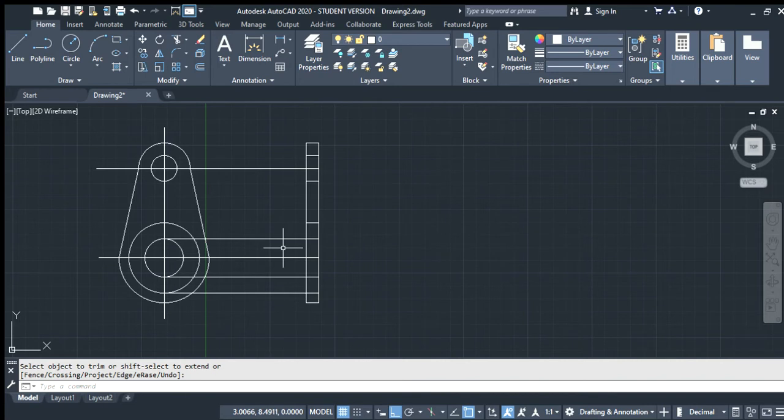The last part we're going to need is looking at the dimensions. We have to draw the actual standoff for the crank. So as you see, it's 1.75. What we'll go ahead and do is I'll hit L for line, enter, select this point, go in this direction instead of this direction, 1.75, enter, and it'll actually give me my endpoint, which I can use to cross off the rest of them.